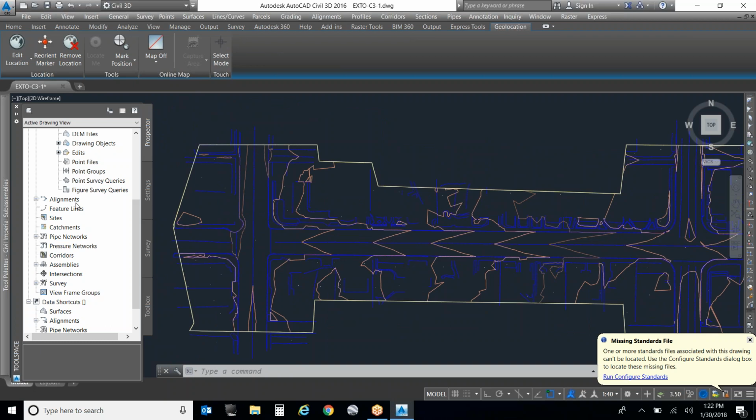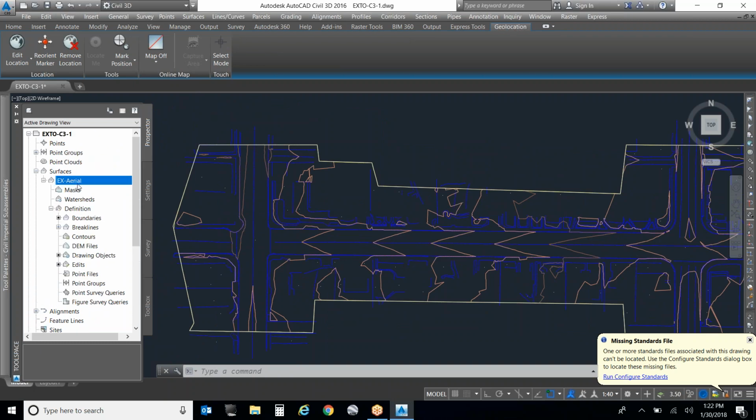Any questions, thoughts, ideas? When you're creating your surface, what's the correct order of operations? You're going down through the list, or should you end with your boundary, or is that the first thing you should be picking? You end with the boundary, because if you add data after you add the boundary, it no longer respects the boundary, especially if that data is outside that boundary. You can't start with the boundary anymore because it wants data before it will let you place a boundary. Correct. You cannot add a boundary to an empty surface definition.